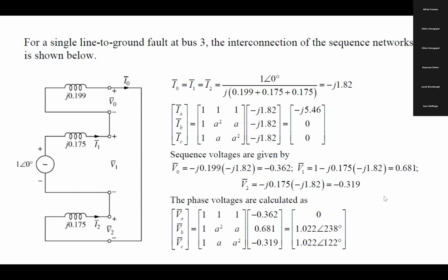Because I feel like it'd be telling from the setup that they're like 2 voltages are the same, they know it's like a line to line, or it lets you know. I don't know. Yeah, I know what you're saying. Yeah, if it is involving, so if 2 lines are the same, carrying high current, and the same two lines are carrying zero voltage, then it's definitely line to line. Then how you will identify it's a line to line or line to ground is based on the angle. If the ground is involved, then the angle will not be 120 degrees.